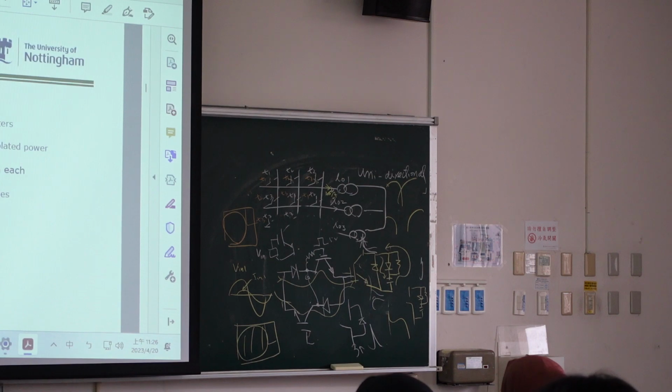No, they need independent supplies, right? So you cannot use the same power supply for this one and this one. Then you have big trouble because they should be isolated. We can control direction: if we use the IGBT, we can control the current to go this way or this way with each switch. So it is useful for most circuits.